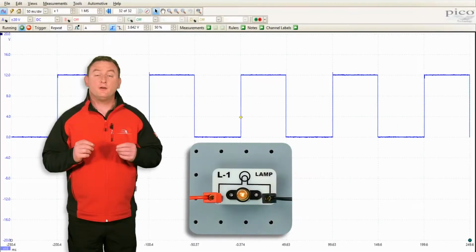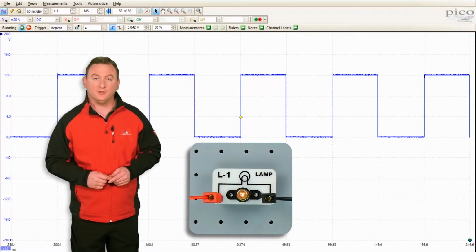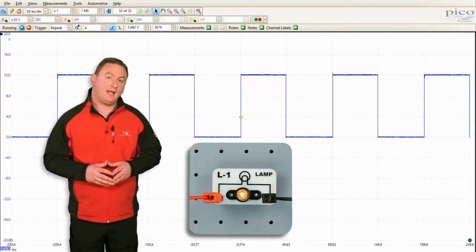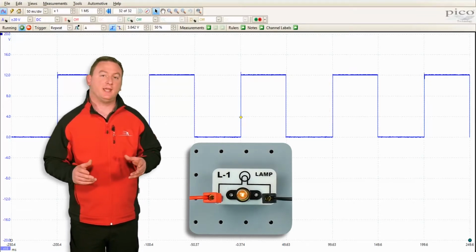Okay, so now we know how PWM is used to control the brightness or position of a component. Let's concentrate on the measurement. After all, if you are looking at something like an EGR valve or a motorized throttle as an example, you may want to see what the PWM duty is and compare that to the physical position of that actuator. There are a few methods of testing a PWM signal. One way is to use a voltmeter. However, it's not a very accurate method, as a voltmeter will display the average voltage that it's seeing.